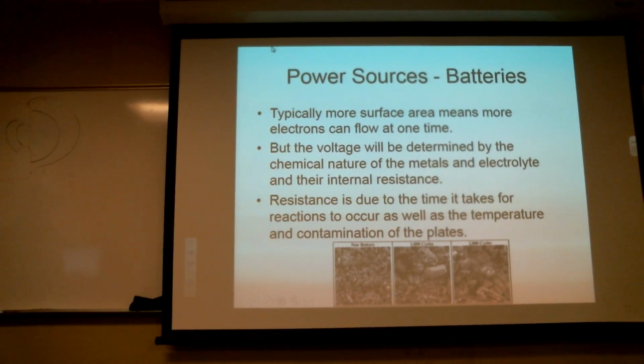They're really high maintenance. Is the new battery still going to corrode and fall apart like that, without having all the cycles? A new battery will self-discharge. In fact, the worst thing you can do to a new battery is not use it. That's one of the problems we have here. I take a new battery, throw it in service, and start it two or three times a month or more. Typically, I'll get anywhere from 5 to 8 years of life out of it. These, where we don't use them that much, I'm hard pressed to get 3 years of life out of them. We just don't use them.